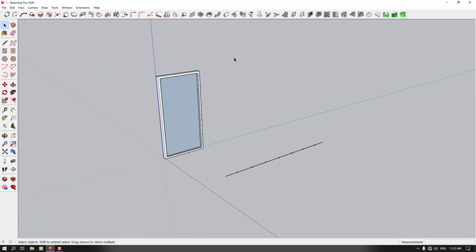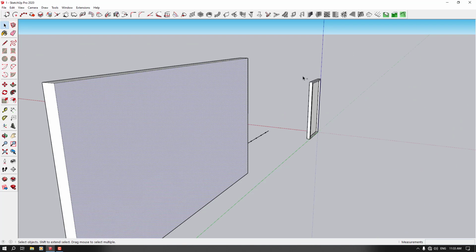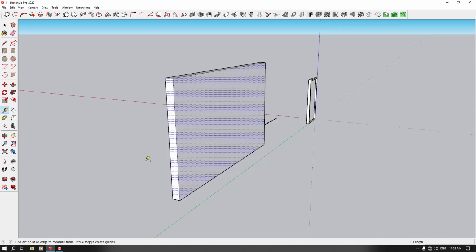Another really useful option in 1001bit Pro is creating horizontal groove lines on your selected faces. For example, I want to draw a wall in this place with dimensions of about 20 centimeters by 500, and now I want to extrude it a little bit, about 300. So I want to select these four faces in here. I want to use the tape measure and add a measure of about 60 and another measure of about 160.